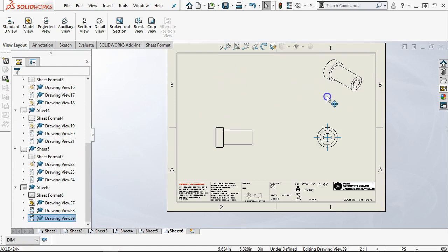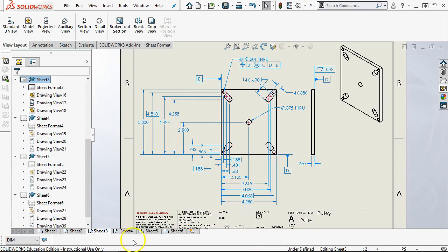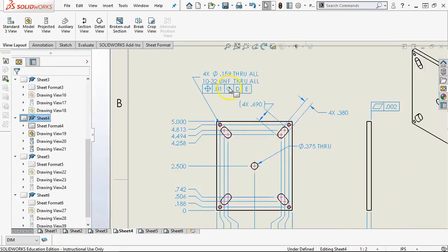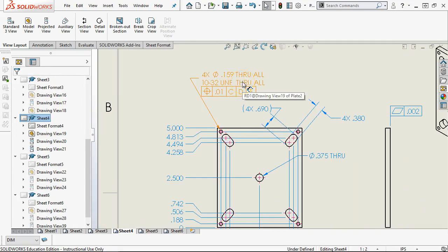All right, so that was something that I jumped over on the discussion for the threaded holes. Whether we're going to do functional gauging. We didn't make any specification or call out of, are we going to do the minor diameter? Are we going to do the pitch diameter? Major diameter really isn't accessible in this case.